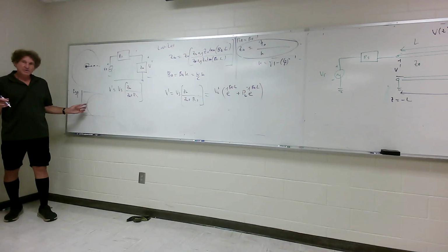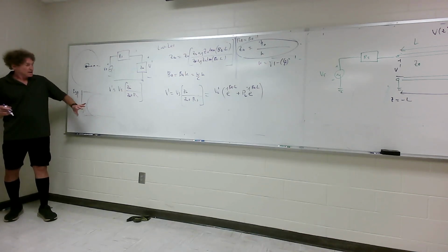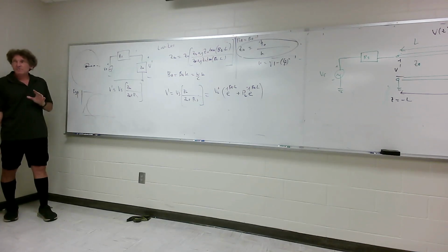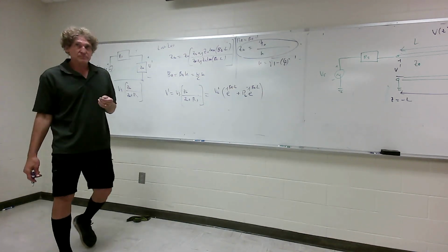And integrate it over here, you're going to find a whole lot more power can be sent with a rectangular waveguide of a given cross-sectional area A times B, compared to what could be sent with a transmission line with outer radius B, inner radius A. You all follow me? And that's real important. So that's the reason we use waveguides. Low loss, we can send a lot of power.